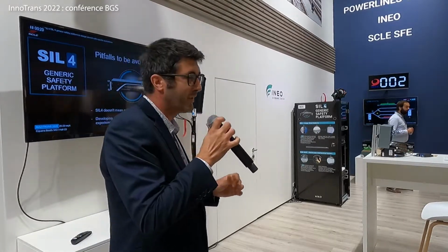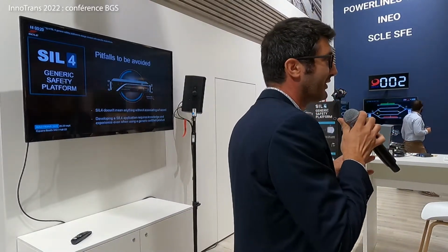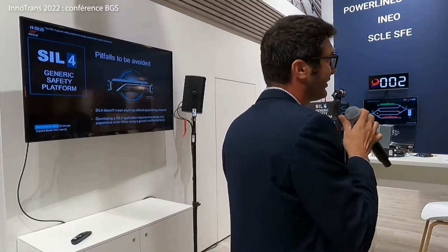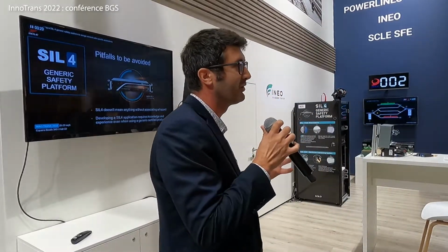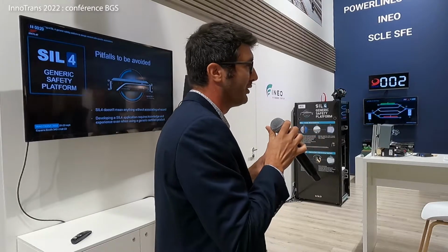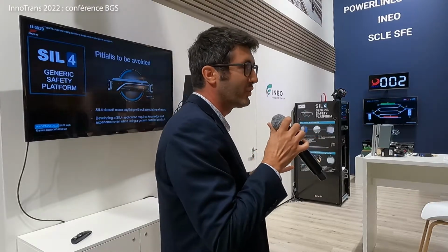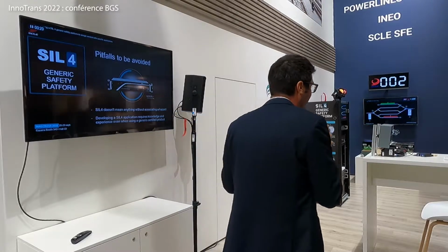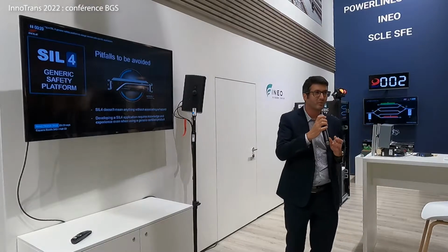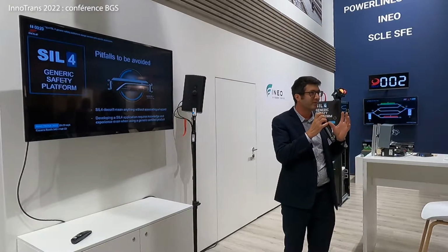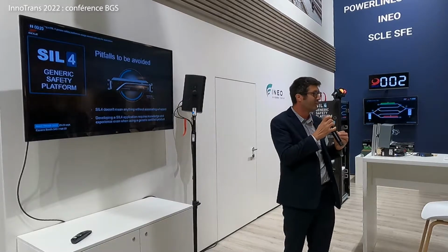Also, there is a major point to know: usually, when you speak about SIL4 or safety, we say we need a SIL4 project, but we really need to associate a hazard to the SIL level. It's really common to say, okay, we need to do a SIL4 project, and when we ask what is a hazard, people don't really know. So it's quite important because if you don't have the safety culture, it can be complicated to know what to do and what to plan.